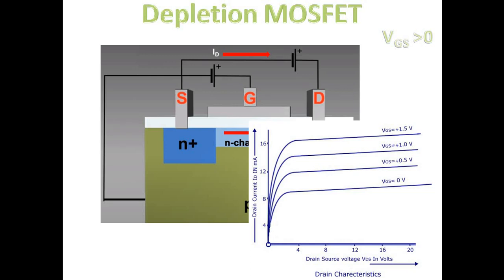Okay, so if I now consider this scenario of VGS equal to positive, I can actually get currents which are higher than IDSS. And that means that the main difference that we see here from JFET is that you can have saturating currents even higher than IDSS. Okay, so VGS equal to 0 volt is not the ultimate limit of the maximum current flowing into the circuit.